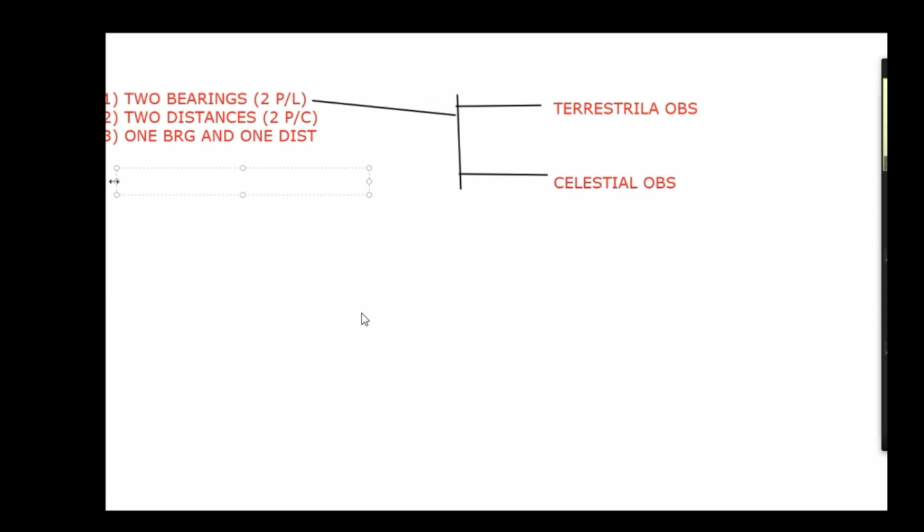Maybe 15 stars are available, but some of them are not very bright. Dim stars are very difficult to take. So we take bright stars, Sirius, Vega, Antares, anything, Jupiter or Venus, if the planet is available. So we choose the bright stars. And after that, we don't take many stars. Only 3 stars is good enough. And the 3 stars we generally calculate, and we get 3 position lines, and the intersection of the 3 position lines is the position of the vessel.